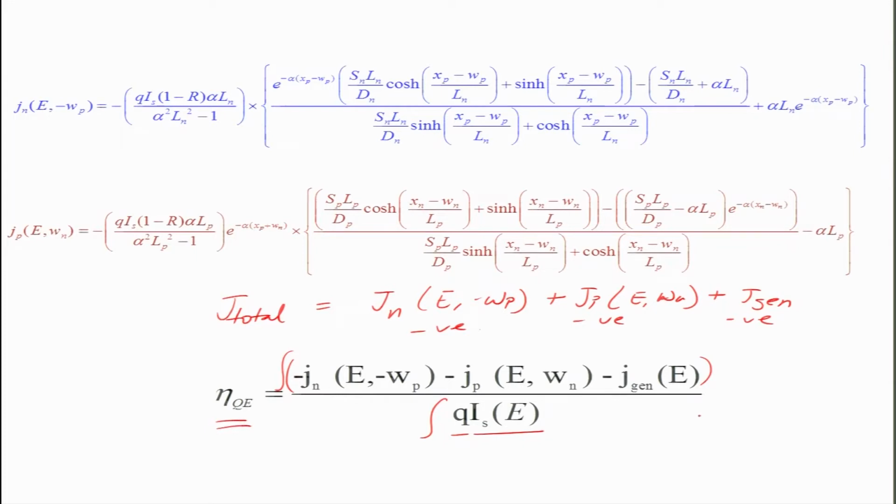Okay. Suppose you had 100 photons falling here, 100 photons will give you 100 electrons plus 100 holes, right. What you get here will be some other number, x electrons and some y holes, let us say, because of differences in electron and hole current, they are not similar. So the ratio of current corresponding to this with respect to what should have been ideally created is the quantum efficiency.